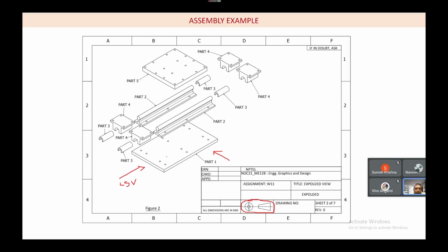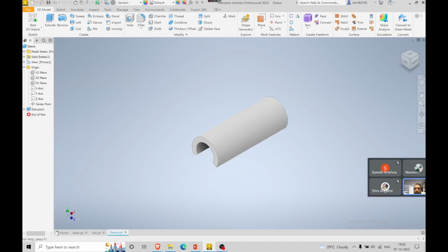So again in the new, I open, okay, create a new sketch. So this time also I am going to create it in the left side view. So this is left to me, so I select this. So first I want to select a rectangle.